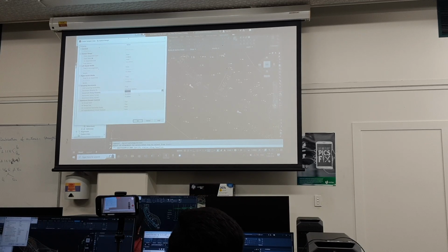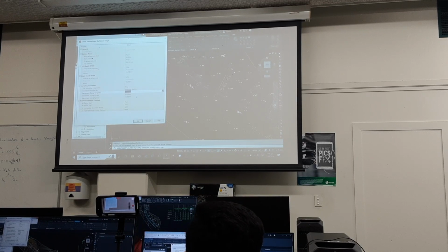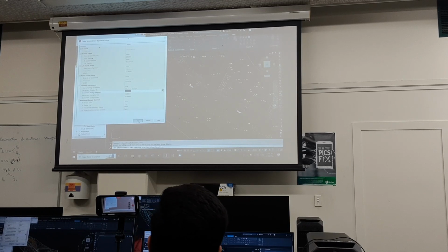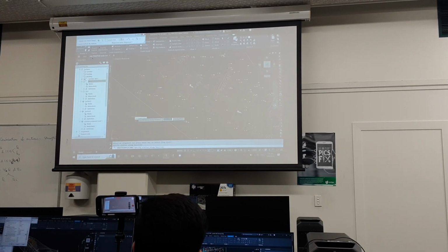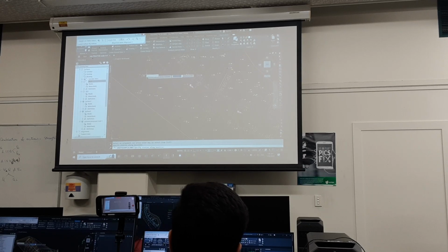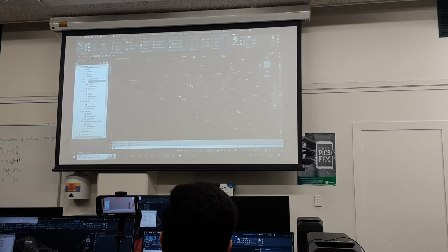So I've now got everything at 10 meters, like I said before. In the assignment, I think it's also 10. If it's not, change it accordingly to what I asked for. So I'm going to go OK to that. And guess what? All the lines have been put into place. Now I can escape out of this, and just escape out of that.